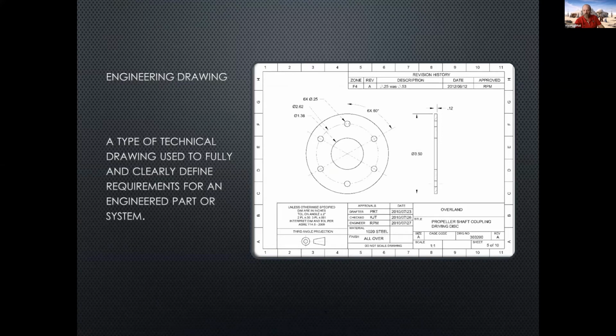So this is telling you what kind of materials to use, typically, specifically where the holes are drawn or made, how thick things are, the placement of any kind of key features. Okay, here it's telling you it's steel, it's 1020 steel. The tolerances, which you'll learn more about later in the semester. Okay, what it's called, what the company name is, and then who drafted it, who checked it, and who signed off on it, the engineer who signed off on it.